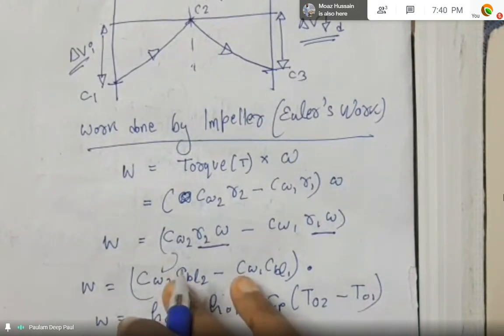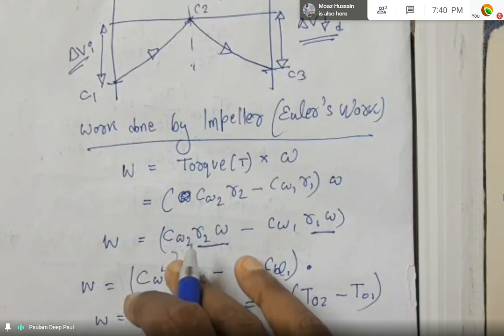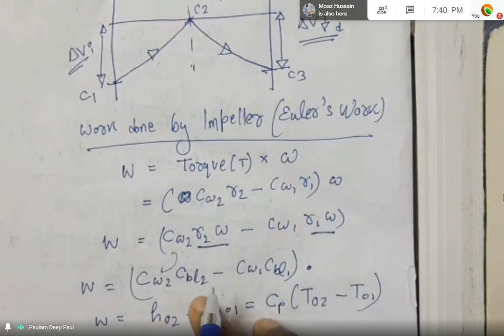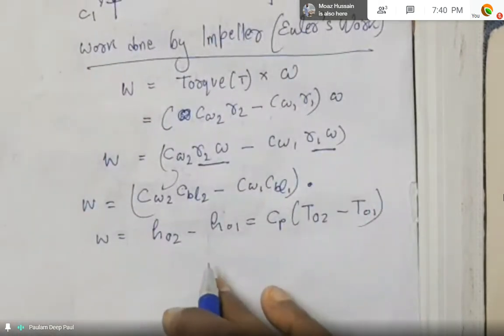Enthalpy, as we know, is the summation of internal energy plus the product of pressure and volume. Since there is a change in pressure and subsequently volume, and also in the internal energy of the incoming air, we can express the work done in terms of the enthalpies also.